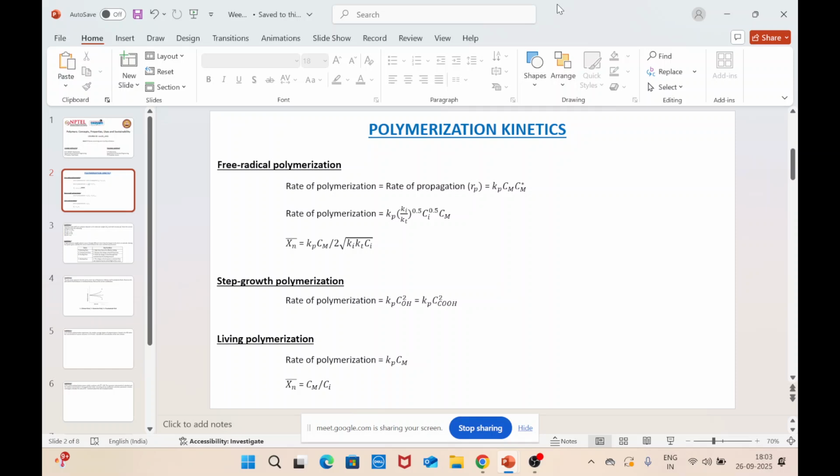Once this cavity is filled with the polymer, the sample is cooled along with the mold and is allowed to solidify. Once it is solidified, the mold is opened, and then the part is ejected out. After this, the process again continues. So this process is injection molding. It's a very simple process.